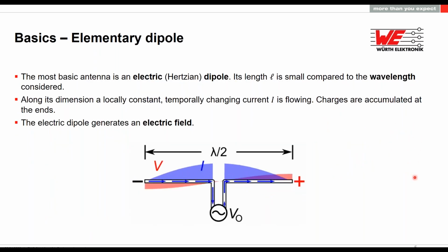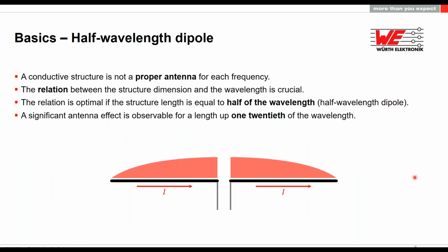So every part that is in this range could be radiating this noise. For example, if we are having noises with a really long wavelength, meaning low frequency, most likely we will have radiation coming out of the cables and long parts of our device. It would be cables, housing, and so on.